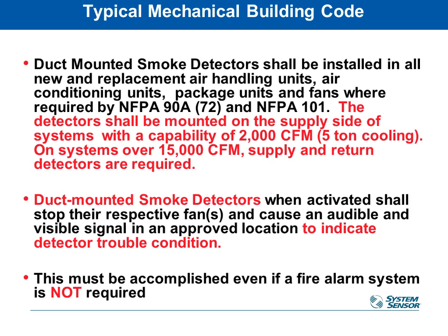We'll talk about IMC in a minute, but the NFPA requires that you mount the smoke detector in the supply side of the system. So that would be after the heating and cooling sections, after the fan. The very last thing in the system before air is delivered down the duct would be the smoke detector. It can be located inside the rooftop unit, or it can be located in the supply duct system itself.